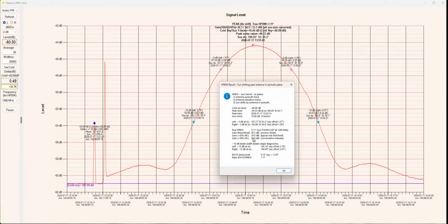And this is an estimation of the gain, and normally you would pick the one in the center here at 65% efficiency of the feed horn, which gives 34.5 dBi. Smaller dishes of 1.5, maybe 1.8 meters, you will probably end up around 50% efficiency, depending on the feed horn, because you have a lot of blockage. But it depends a lot on the feed horn, of course.